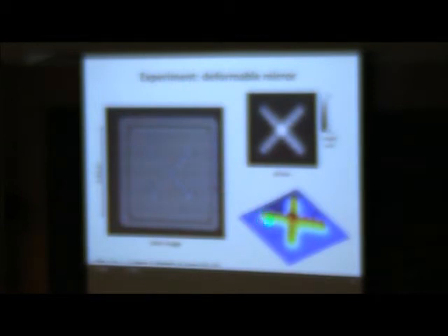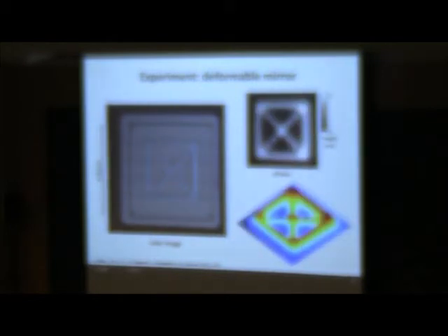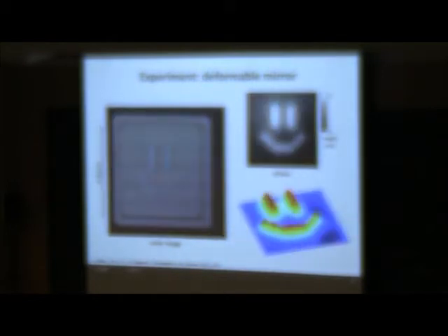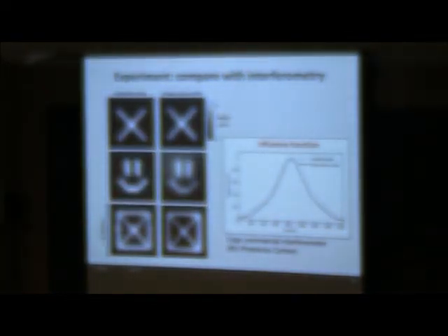So here you can see the actuators. This is actually inverted. They're actually pulling down instead of pushing up. But you can see the little tents they create between them. It's a couple microns high. And then this is dynamically changeable, so I was just having fun. But it compares very well to commercial white light interferometers. This was a Zygo that we compared to.